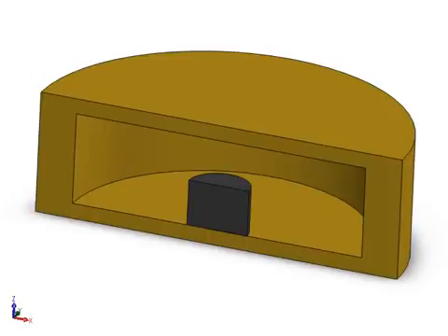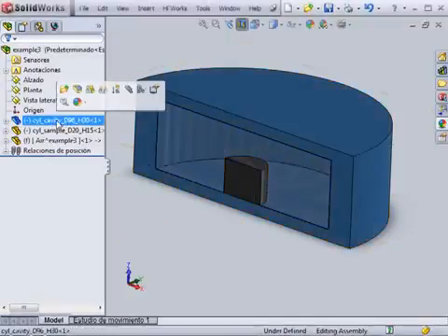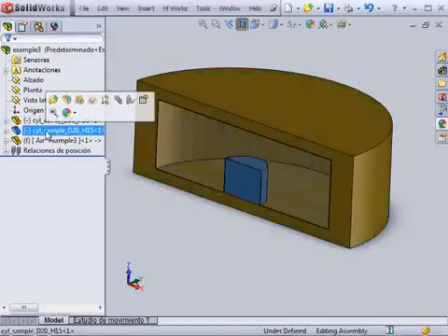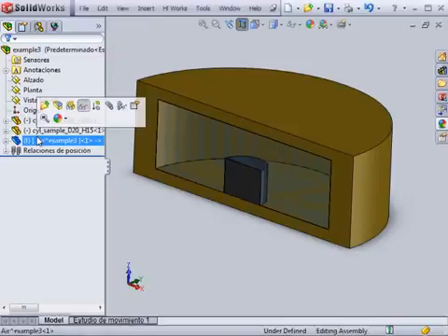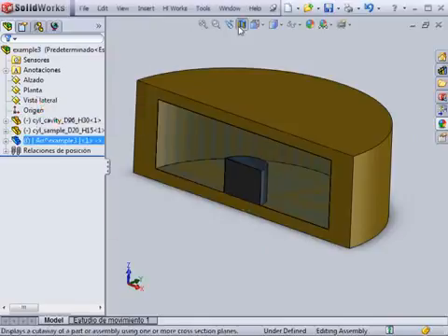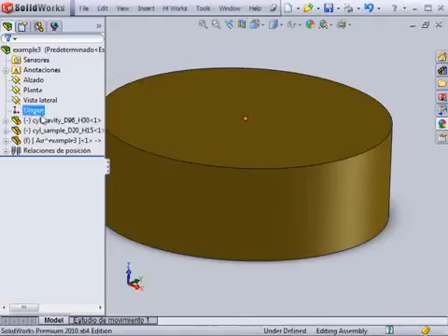The model consists of three parts built in SOLIDWORKS: a cylindrical cavity, a dielectric body, and the air inside the cavity that surrounds the dielectric. The analysis will be performed by removing the metallic cylinder to reduce the computation time.